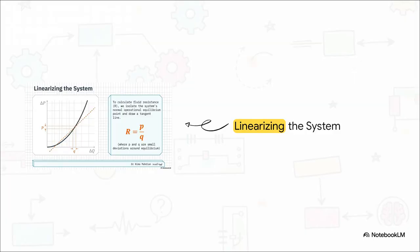To actually solve this, we isolate that normal operational equilibrium point. You know, that sweet spot right in the middle of the curve where the system usually runs. By drawing a straight tangent line through it and sticking to microscopic deviations around that point, which we label lowercase p and lowercase q, we can safely pretend the system is linear. So our fluid resistance, R, becomes simply p divided by q. It's an approximation, sure, but it is an incredibly powerful one that totally saves our mathematical model.